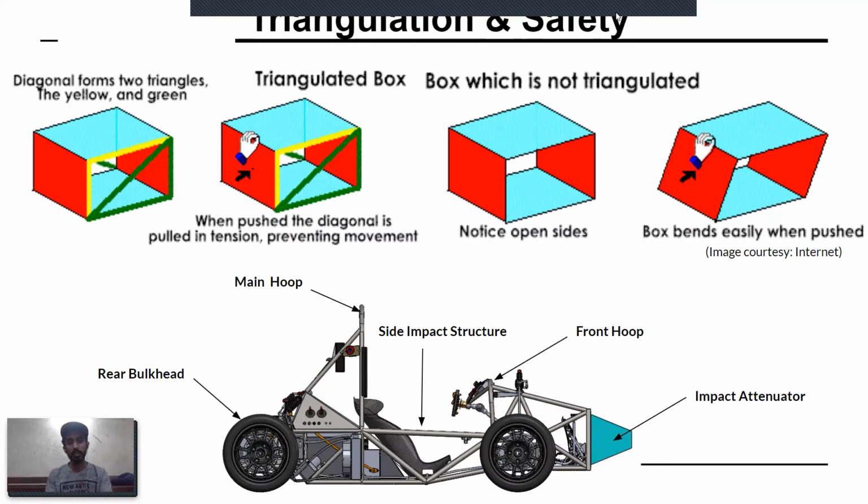Triangulation and safety. Besides being a separate department, all the other systems are related to the chassis design, mainly suspension. Hard points or suspension points are the points from where the road loads will be coming to the chassis via the suspension system. It becomes the goal to achieve suspension points on node locations where more than 3 chassis members are being joined together to ensure the proper load path and avoid chassis tubes going into bending. For tractive system components, the goal is to accommodate them within the TS protection structure to protect them from any kind of crash or side impact or even contact during a rollover.